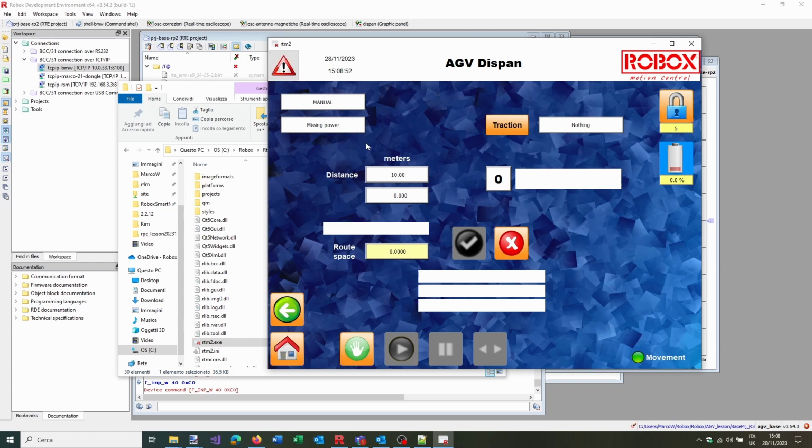So it's checking the circumference, and you are making it very, very precise. You must do this procedure the first time you switch on a new AGV for the first boot, and then you will save. In case you do maintenance on an already existing AGV and you substitute wheels, remember that the new ones will be, of course, wider, because all the old wheels have suffered wear and have been scratched, so their circumference is smaller, and for this reason you will need to do this procedure again.